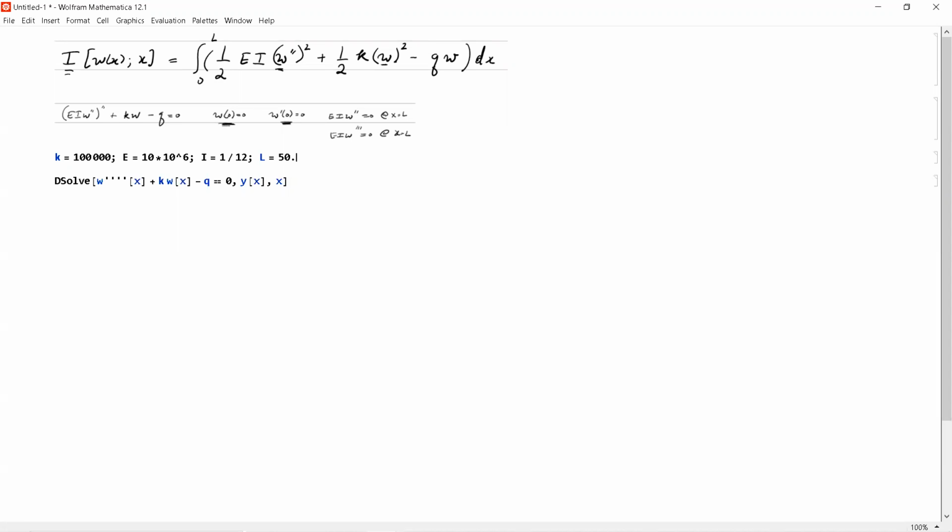And I think that should be enough to survive. And let me just define EI. Mathematica is going to have a problem with this I, so let me just call it double I for inertia. If you don't mind, EI is going to be E times double I. This big E may have trouble too, so let me just make a double E here, because E is the exponent maybe. I don't know if it's true, but I'll just do that for now. So that's what I get.